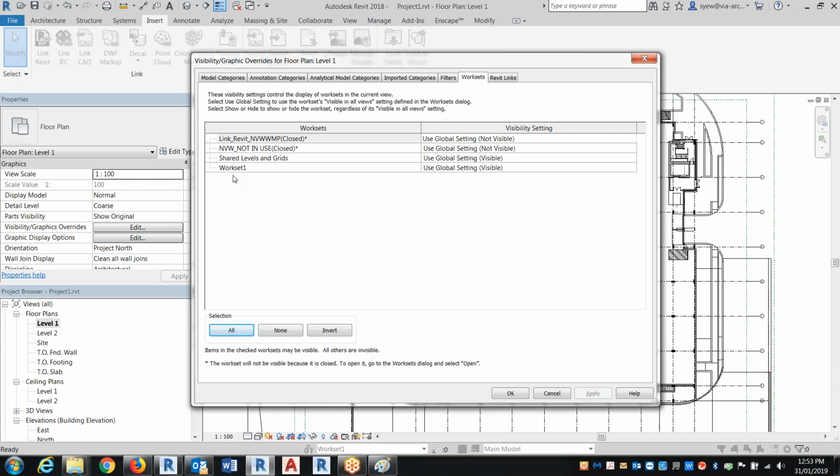But once you get to more of a coordination stage, where a lot of details and information need to be coordinated, then you have to start thinking about breaking it up into pieces. If it's interior, it's interior. If it's exterior, then you put it in another Workset. If it's anything related to structure, you put it under structure, or you can put it under their Workset so that they have easy access. Other than that, I think that's pretty much it. This is something that still needs conversation, because not everybody understood what Workset does, and nobody has actually worked with consultants that use multiple different conditions. So this is where Workset becomes very, very useful.